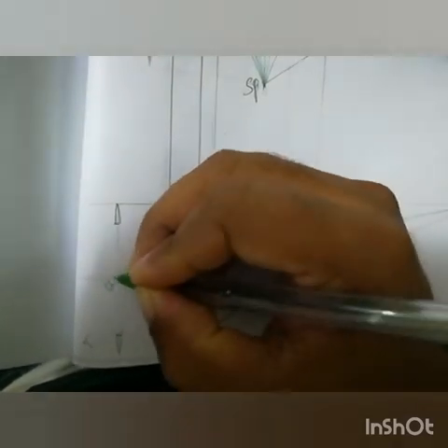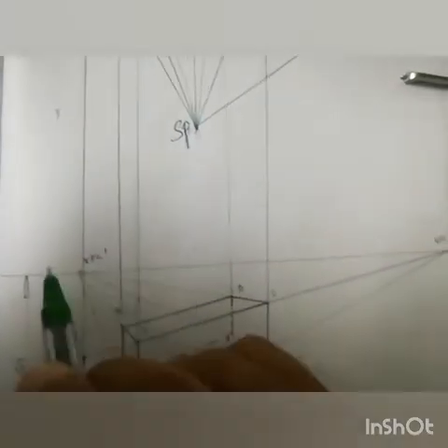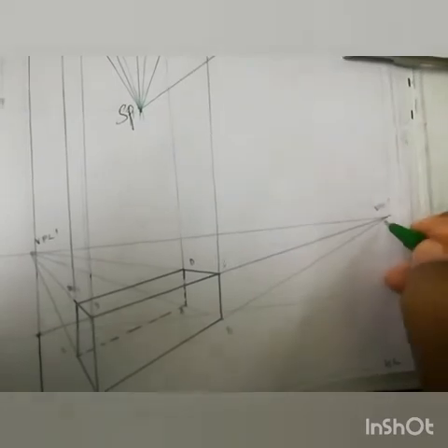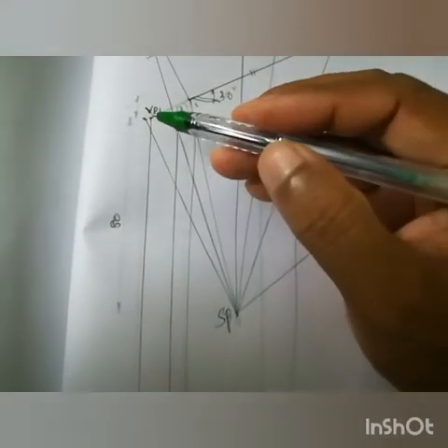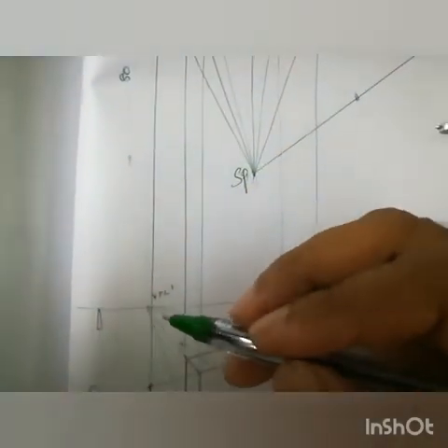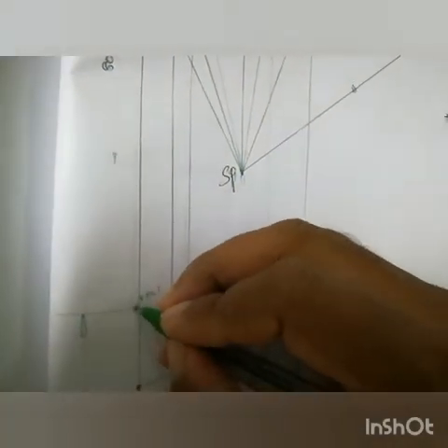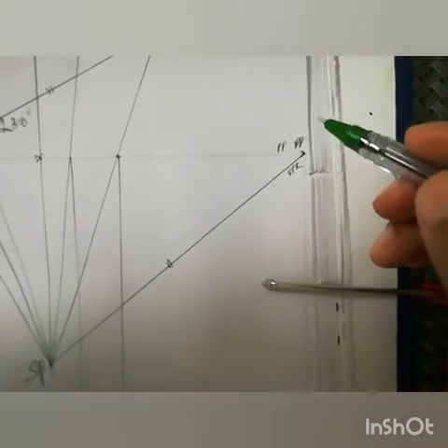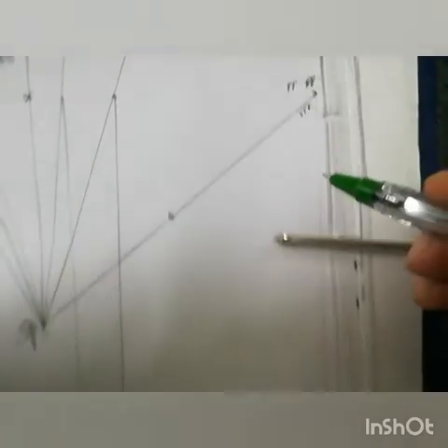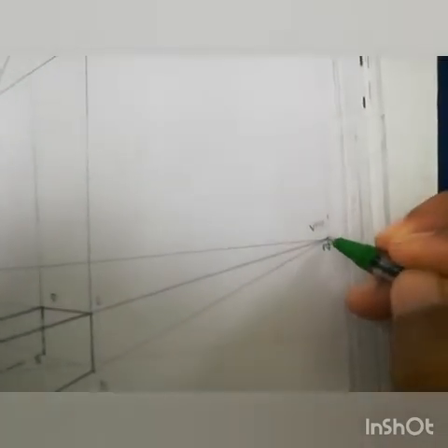So this is 60 mm. So you draw a horizon line, HL. Now from VPL you draw a line to the horizon line. So this is called VPL dash. Similarly, from the VPR you draw a line, so that you will get a point called VPR dash.